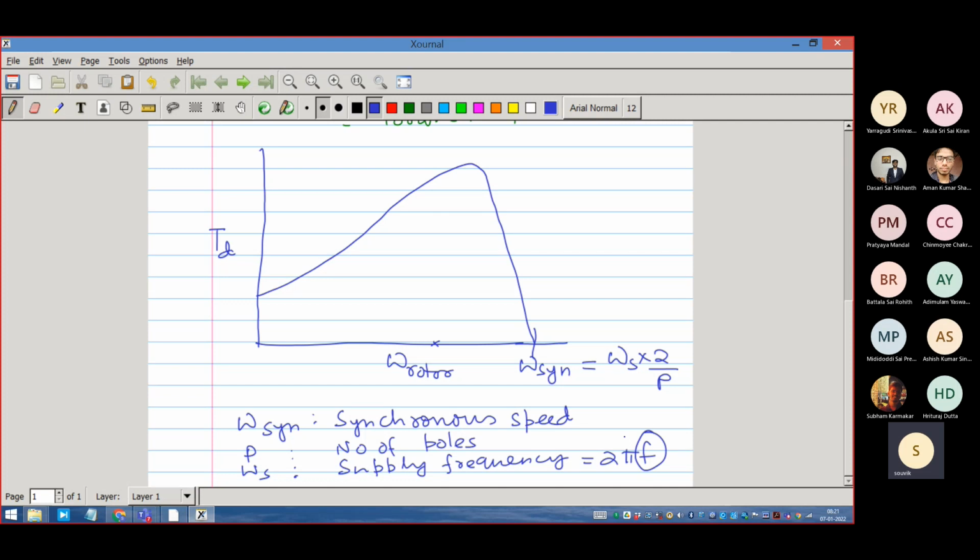I will show you how, but for the time being, let us say what we intend to do. We want to shift the characteristic like this and change our operating point. The operating point would now look like the characteristic of the overall mechanical system from our perspective, in the torque speed plane.